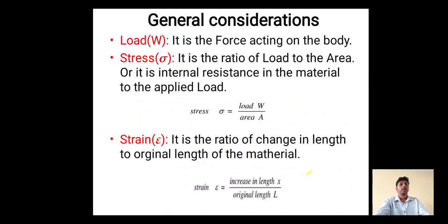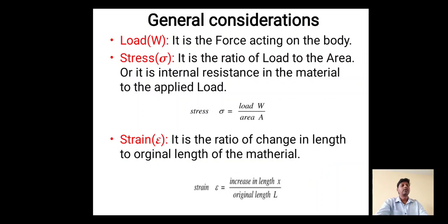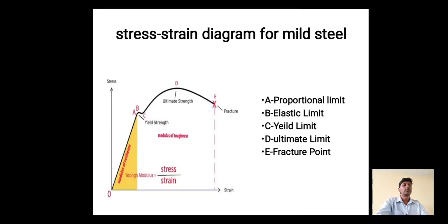Then strain. Whenever you apply a force, the body or component will deform, it will change its length. The change in length to the original length: originally suppose it is 50, now it has changed to 75. The difference is 25, that is the change in length, 75 minus 50. Change in length to original length, 50 is the original length. That is nothing but strain. So we have discussed what is stress and strain.